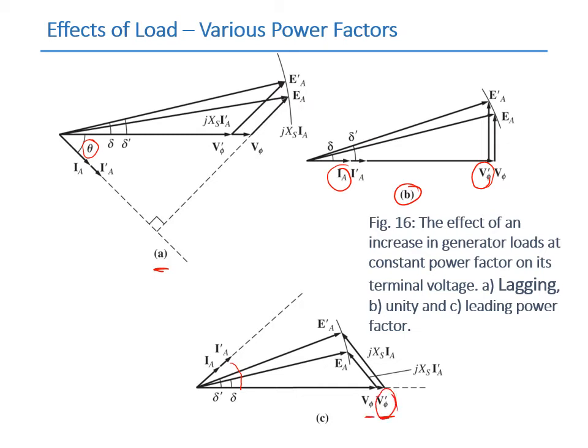So in order for us to be able to determine what will happen to the phase voltage, whether it increases or decreases, when the load is increased, we need to know the power factor, and that's why in the previous slide we already stated that the behavior of the synchronous generator depends on some factors, including the power factor of the load.